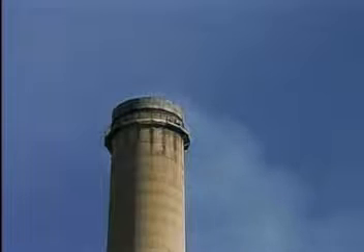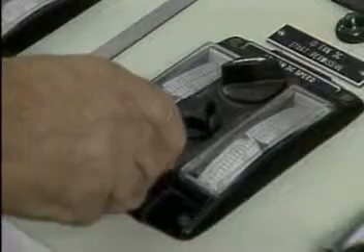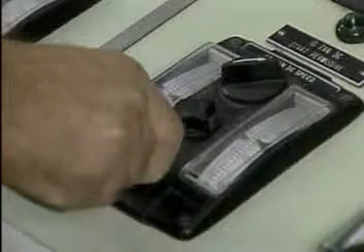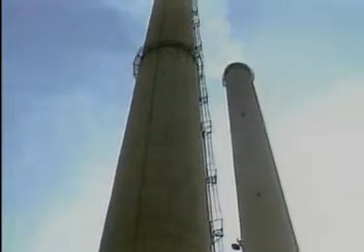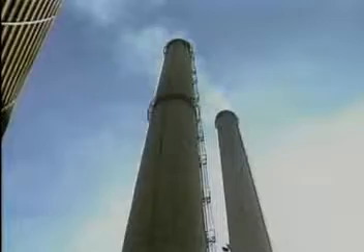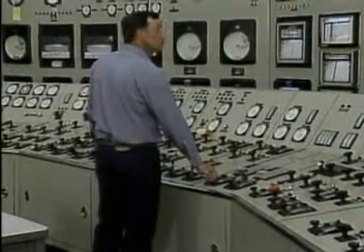The correct ratio is often maintained by monitoring the amount of oxygen going out the boiler stack. If fuel and air could be mixed perfectly, you could adjust the mixture so that exactly the right amount of oxygen would be supplied to allow the fuel to burn completely. All of the oxygen would react chemically with the fuel, and no oxygen would exit through the stack. Unfortunately, however, achieving a perfect mixture of fuel and oxygen is impractical.